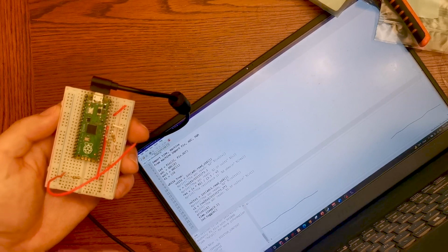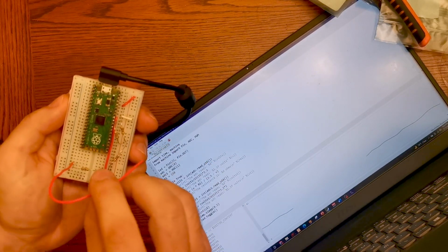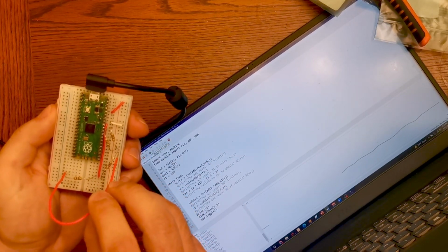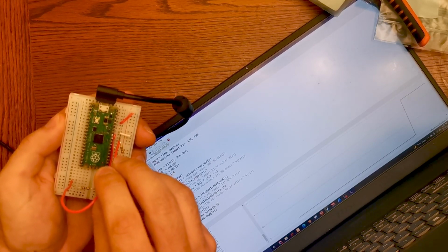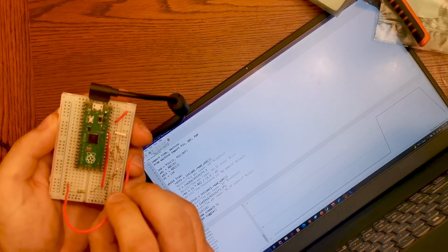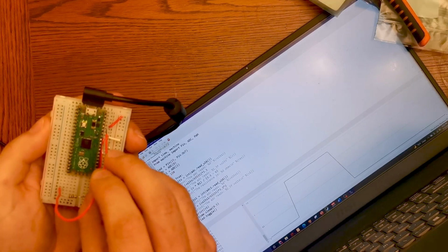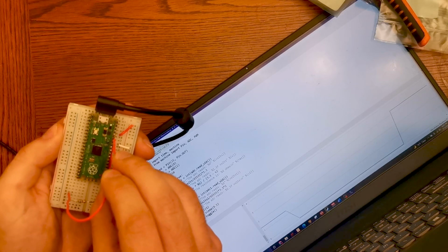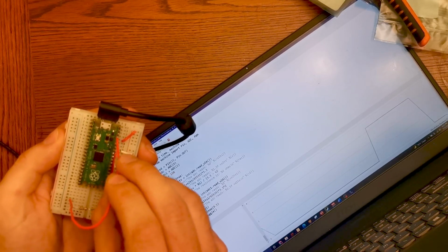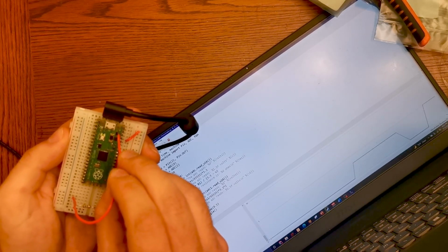In this video, you can see where we're going to be using this probe to probe different portions of the board. The first one is the middle of the voltage divider, which shows you about 1.3 volts. And the next one is going to be the output from the Pi Pico, which is about 3.3. And finally, it's going to be the USB, which is about 5 volts.